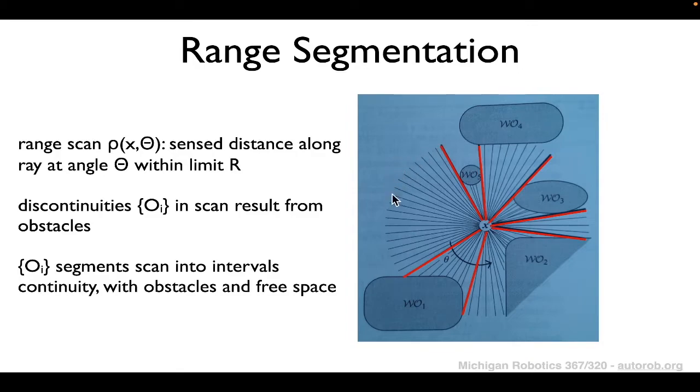You can see all of these rays, for example, have reached their range limit, and so they're perceived as being directions of free space, whereas the discontinuity between the ranges that have reached their limit and these ranges that are shorter than their limit correspond to obstacle extents. So these red highlighted rays correspond to the detections from this sensor that represent the obstacle extents our algorithm is going to be using. These interval discontinuities are how you could perform this segmentation efficiently.